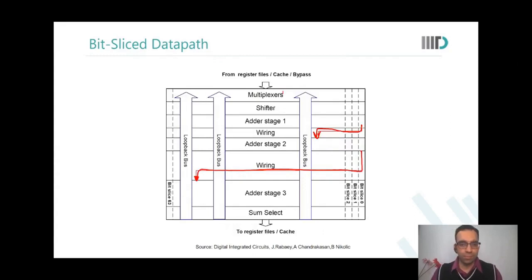Sir, just a clarification. If I have a bit slice, let's say a very simple circuit of a mux, so in a bit slice, we can say that output of many bit slices can converge into a single one, like in a multiplexer, many inputs are there, there is only one output. Not necessary, Gagandeep. It could be that I have 4 inputs coming for every multiplexer, and those 4 inputs are available separately for all the bits. And I select just one out of those.